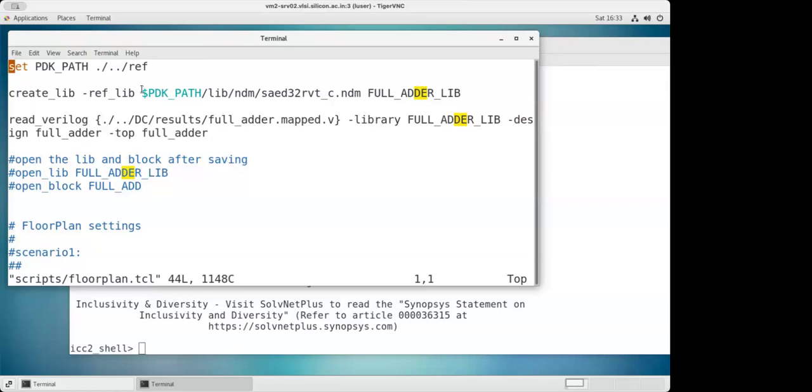You can tell the tool, okay, you map everything, now you save this, whatever the database, and you save it in one place. So the tool can save that particular part. Now maybe in our case the .lib file and .db file are small, but in industry a single .lib and a single .db file is around 1 GB, 2 GB. That means it has a lot of content, and we are not talking about 1 or 2 files.